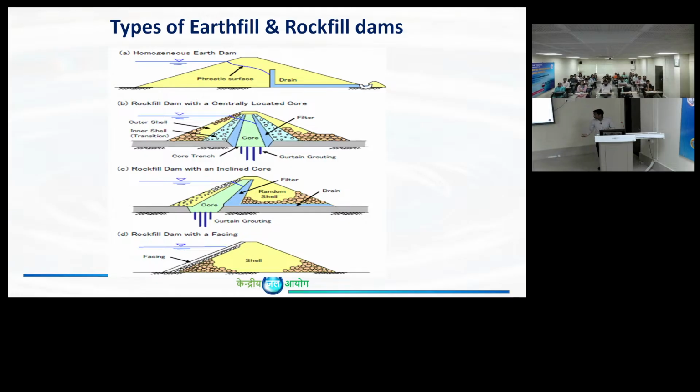So further improvement: as we are increasing the dam heights, these homogeneous materials sometimes fail. So further we have updated it with the core materials. At the center we placed the core material, so we have reduced the seepage. Then nowadays, we are completely shifting this core to the upstream. It's not a core, it's a concrete facing or a geomembrane facing.